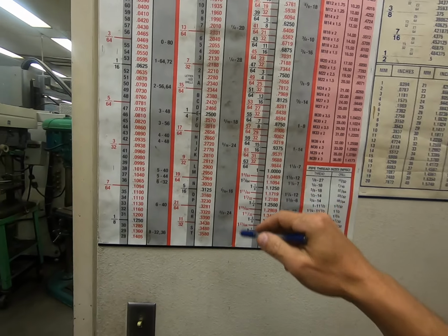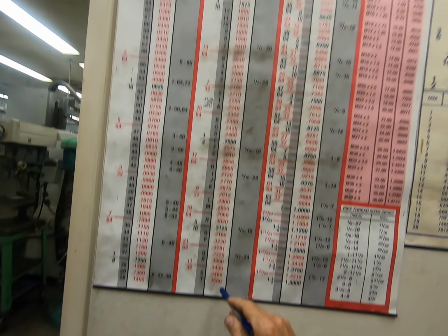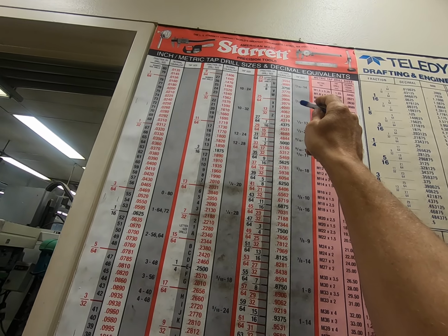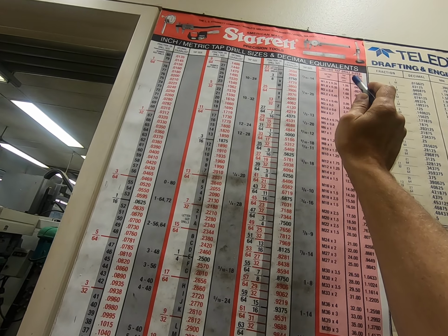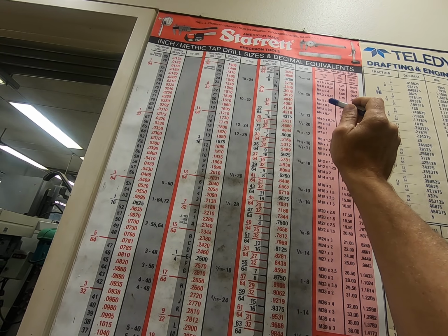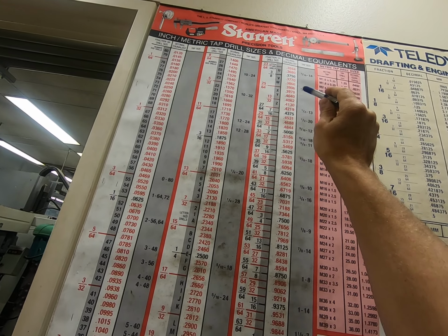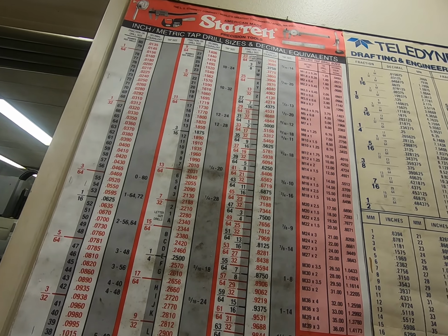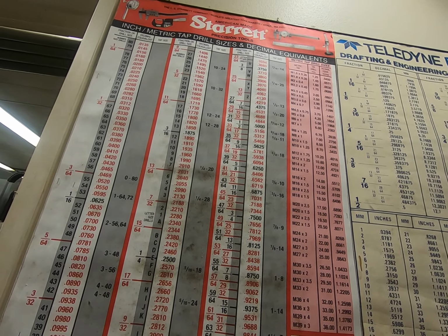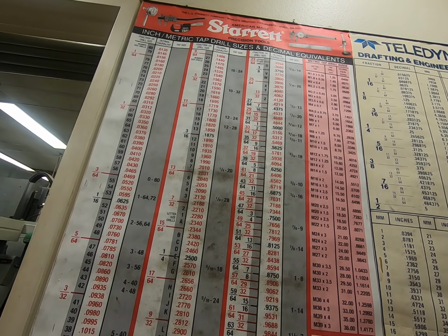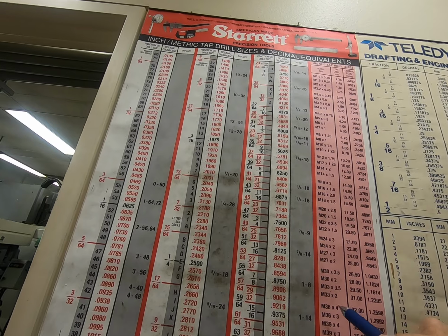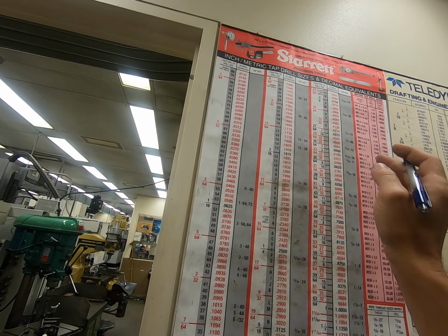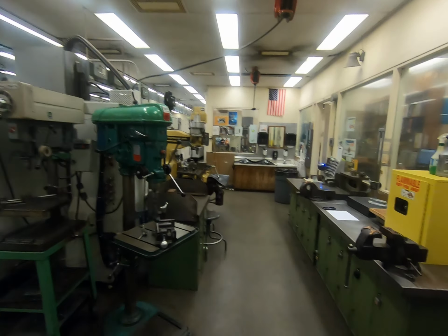If I look at this here, I'm looking at options around 358, then it goes up here. The closest thing I have is a V, which is 377, but unfortunately they don't make end mills in that size. But what we do have right above it is a 3/8. That's 375 thousandths of an inch. So that's a nominal size. Again, that's one of the sizes you have. But that's not quite right, so let's go back and look at it. We're thinking it's 3/8, but is that gonna work for what we're trying to do?